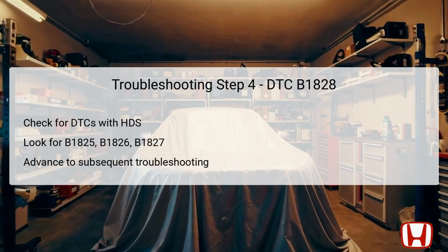Continuing into the fourth troubleshooting step, you will again use the Honda Diagnostic System, HDS, to check for any additional codes, specifically looking for B1825, B1826, and B1827. These codes could indicate further complications within the power seat mechanism. If any of these codes appear, it is imperative to advance your troubleshooting to Step 17, as these related errors could share the same underlying issue.